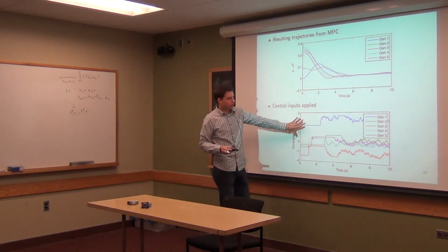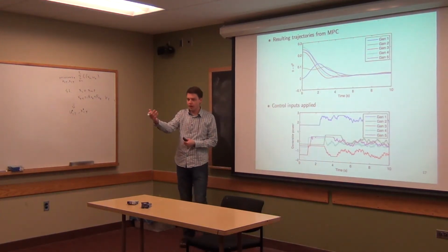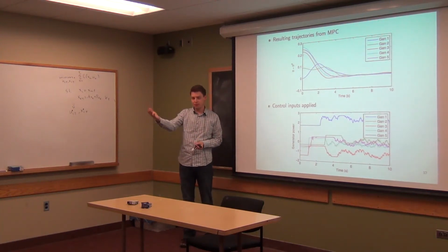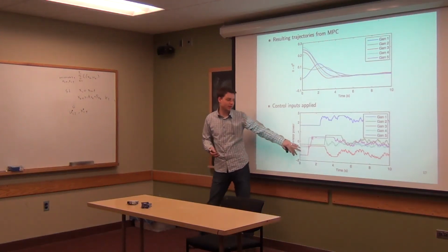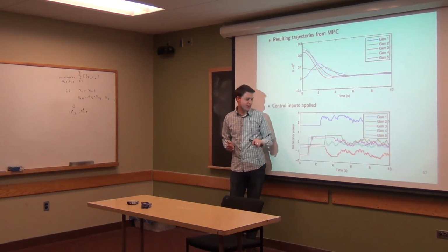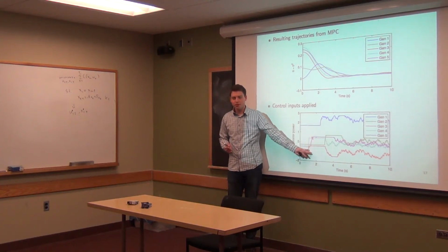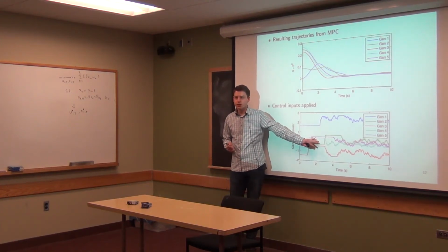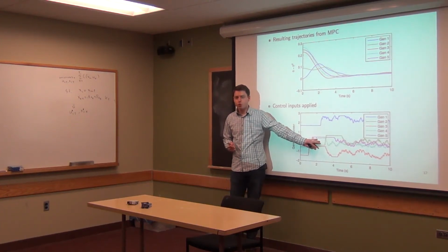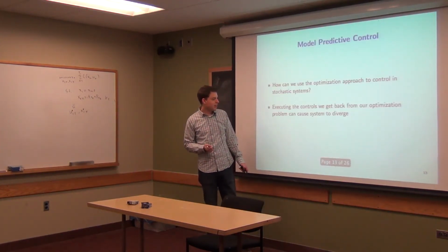So this is what the resulting control actions looked like. And they still have that kind of randomness to them that we talked about before, because there's some random noise. You could smooth this out depending on the cost, but for this particular cost, you still get jagged noise like this. But you get these bounds too, right? Where things are still clipped to their actual amounts here. So you don't have to worry about LQR taking a very big deviation.